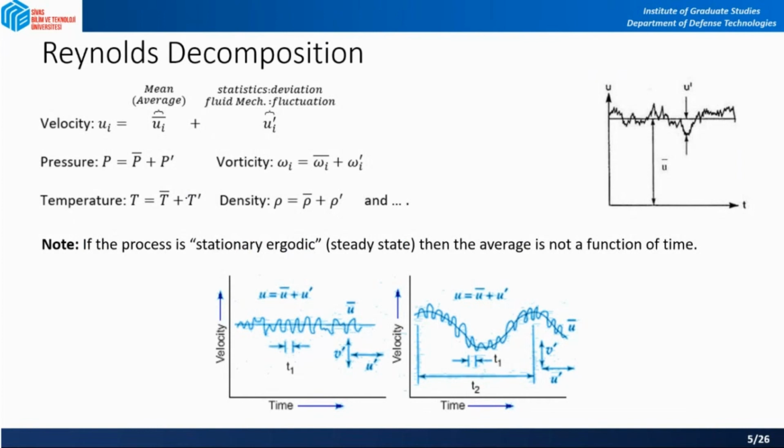So basically, today, similar to the fact that we call the non-dimensional collection of parameters the Reynolds number, this analysis to obtain the average equation set, we call Reynolds decomposition of variables. And this is basically a statistical averaging process applied to equation sets. So Reynolds decomposition: all instantaneous parameters are composed of an average part and a fluctuation part.